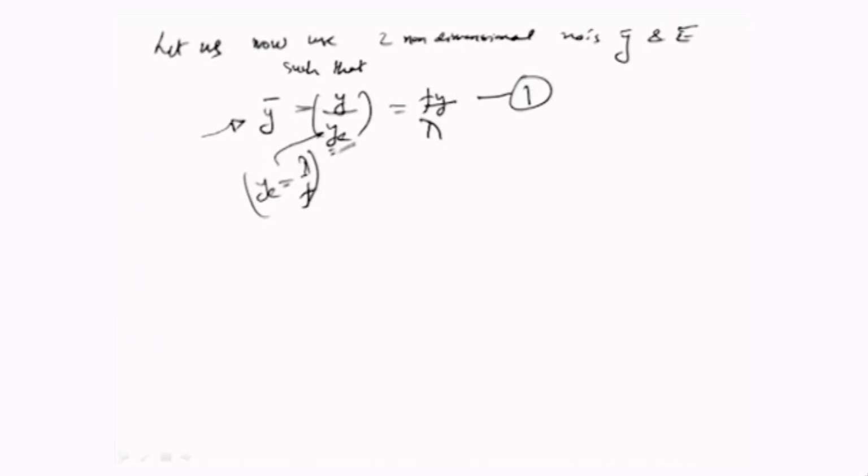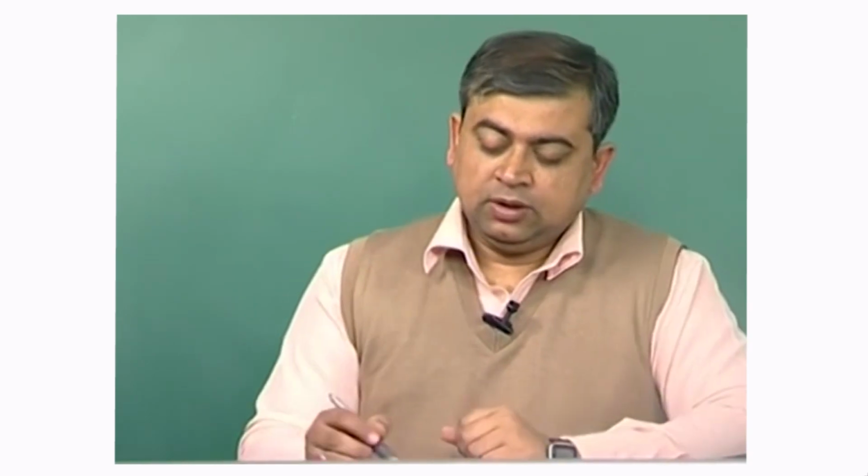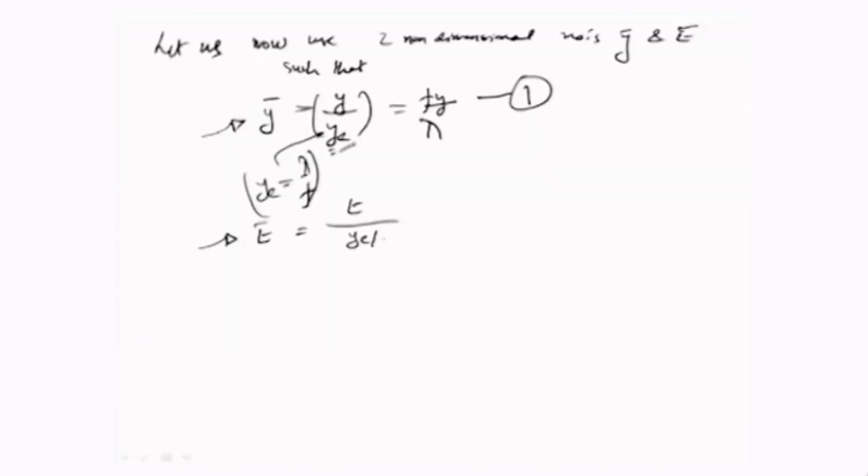At any particular range of operation, it is the scale which varies and the ratios remain the same, and the final equation which will result will be in terms of ratios of those scales. The other thing is the time ratio T dash, which is represented by the actual time that is needed to cover up this equilibrium gap, assuming that the tool is moving at a feed rate of f with respect to the workpiece. So, the amount of time that the equilibrium gap would need to be covered up, if f is the feed with which the workpiece is moving towards the tool, is ye by f.